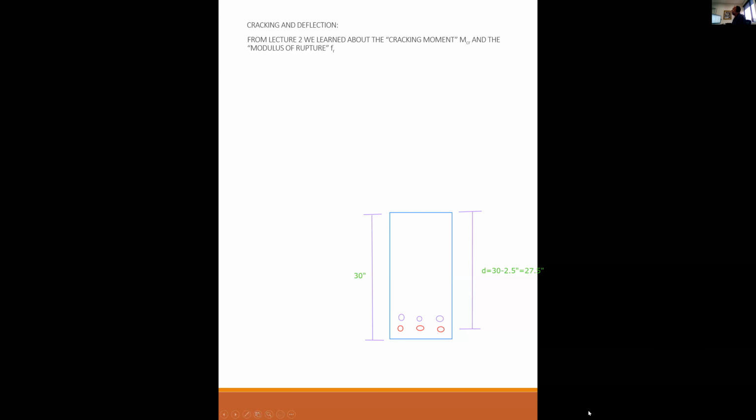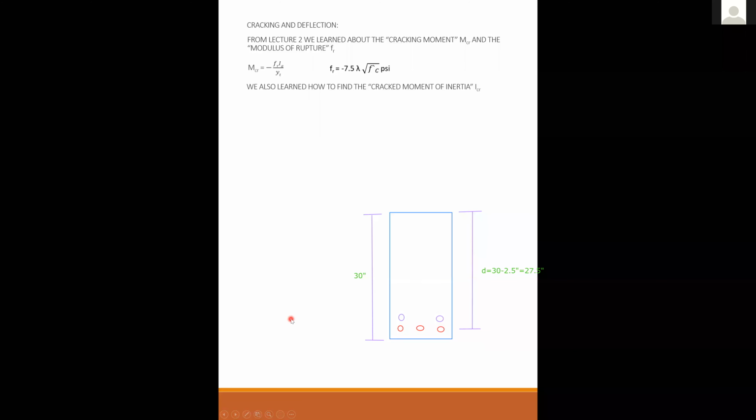Yes. You don't always have to provide an even number, but what's going to happen, I cannot, this is so frustrating. I can't, or I could do this. Okay, how about this? Okay, say that's your rebar. That's totally fine. But what you're going to find is that your center of gravity is not halfway between the 2 rows now. Now you actually have to calculate where your center of gravity is. It's going to be closer to the 3 than to the 2. So that's the only complication of using an odd number of bars.